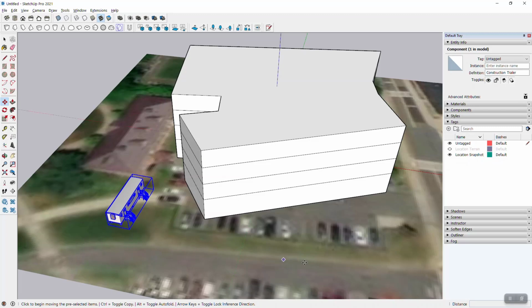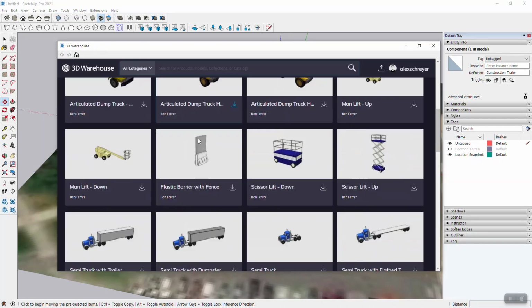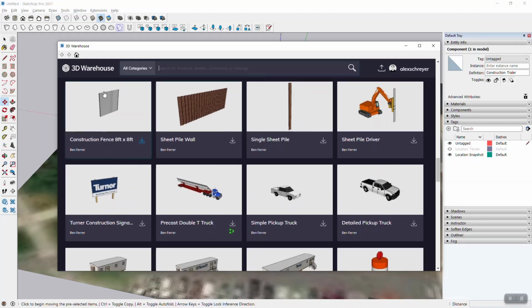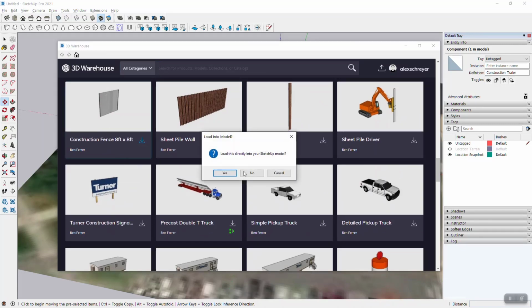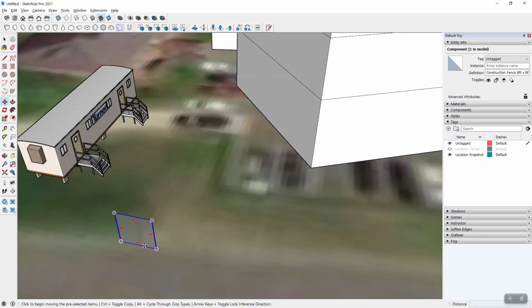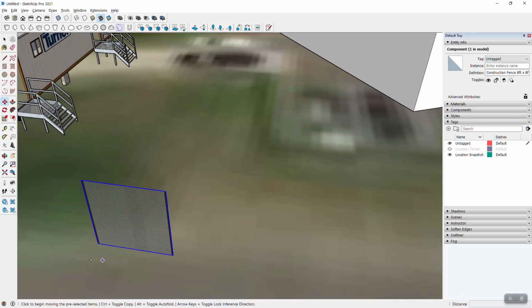Let's assume, for example, that we need to stay away from this road here, and we're most probably going to put a construction fence along that. But other than that, we're going to be able to use everything that's behind. So completely up to you, depending on your project, obviously. Then there's a bunch of traffic control things in there. There's a construction fence. Let's pop that in. I'm just going to pull one in and place it, and then ultimately you'll make copies as needed.